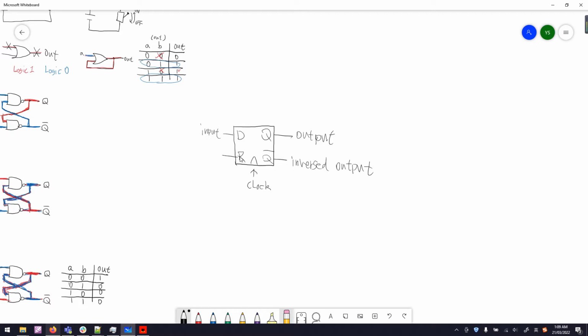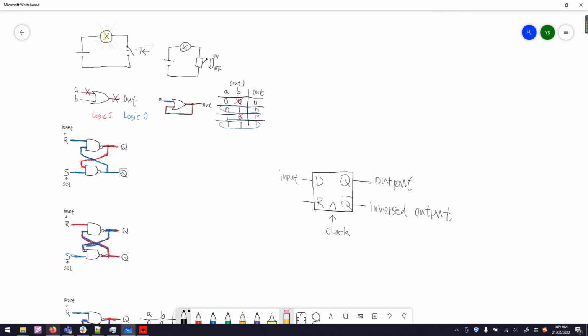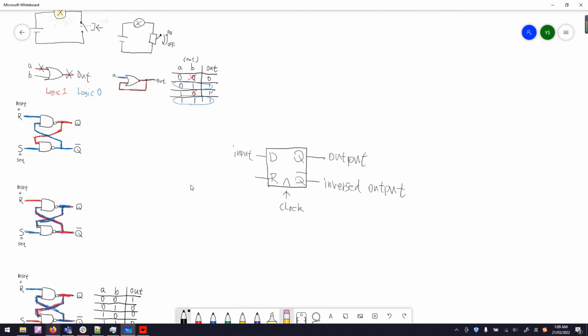We have a reset pin. As we analyzed earlier, when powering up, the states of Q and Q bar are randomly assigned. A reset pin just acts as this reset. It puts the flip-flop at a known state, which is Q equals 0 and Q bar equals 1.